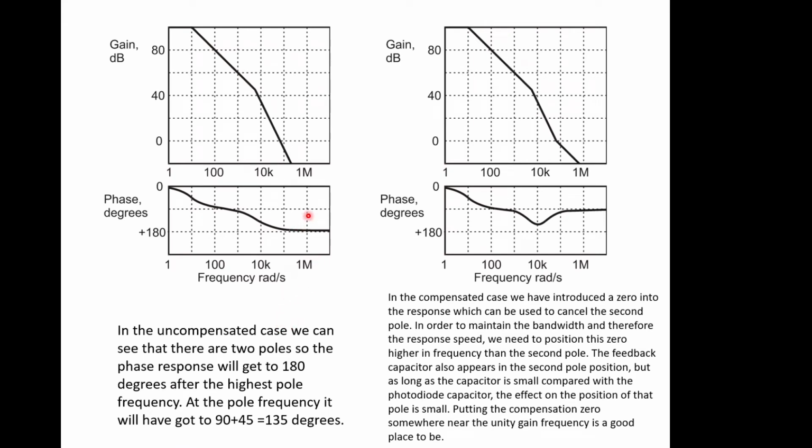Right, so without the 0 we end up with something that doesn't have much gain or much phase margin when we get to this point here, which means that we can start to probably see a little bit of peaking because the op amp can't really maintain its virtual ground. It's got to try very hard, but it doesn't have very much gain. So that's where the virtual earth is starting to break down.